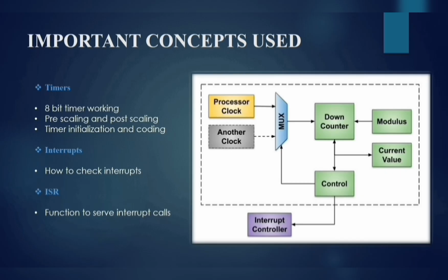We also learned about timer pre-scaling and post-scaling. Pre-scaling is nothing but dividing the input frequency of the timer by a certain number. Post-scaling is just the opposite of it; it divides the output of the timer. These are used to have more control and configure the timing of the applications. Timer initialization is done by setting various configuration options, using the specified bits of the timer in our code.